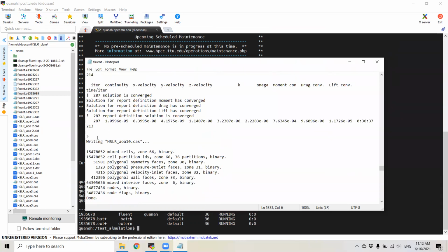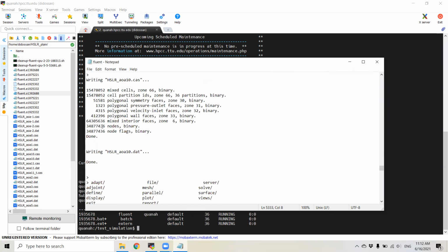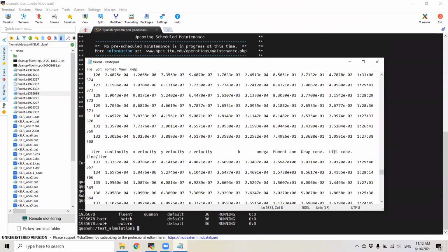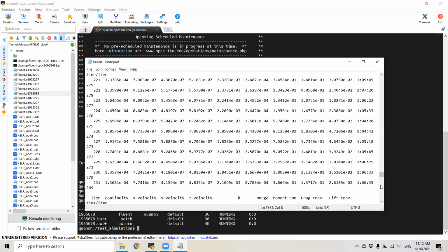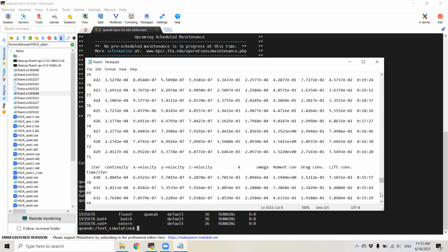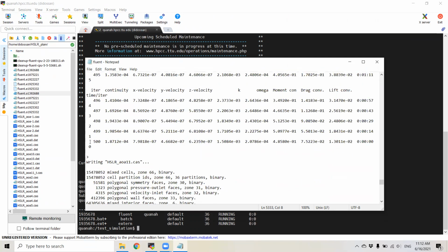So this means that the convergence criteria was met before the maximum amount of iterations was used. And if we drag it all the way down again, we're going to see that that doesn't happen anymore past 10 degrees. So here, for example, the maximum number of iterations was met, which means that the convergence criteria was not met.